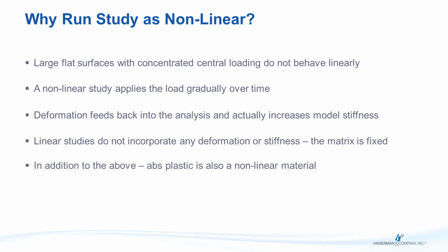Linear studies also don't incorporate that deformation or stiffness into their matrix like the nonlinear does. And lastly, we're dealing with ABS plastic, so it is by nature a nonlinear material.